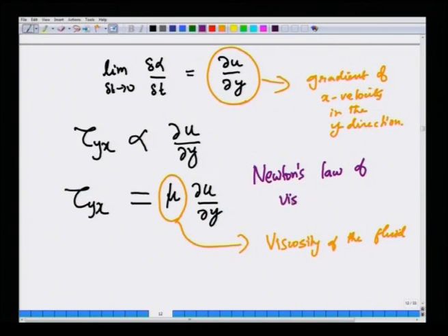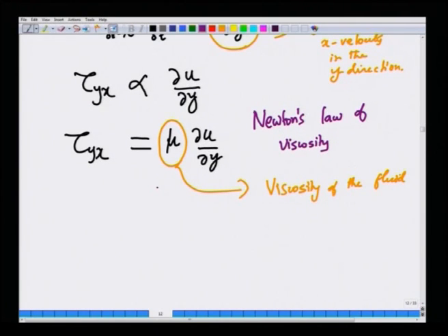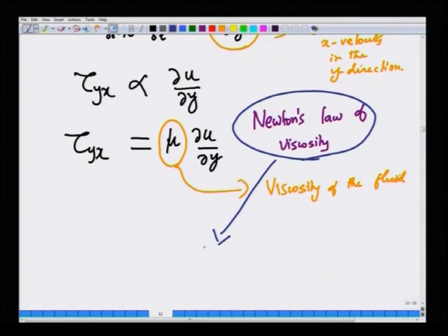Newton's law of viscosity. And the fluids that obey Newton's law of viscosity are called Newtonian fluids. Now, this is not to say that all liquids or all gases should obey this relation, but it turns out that a majority of simple fluids such as air, water, glycerol and many oils reasonably obey this relation.